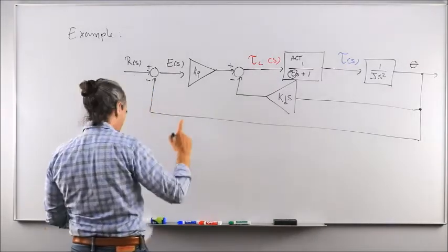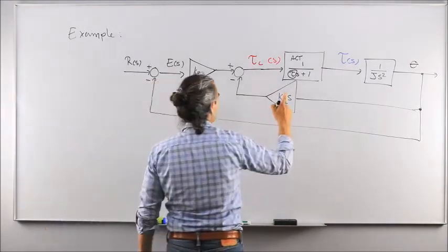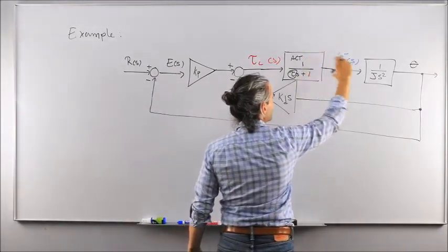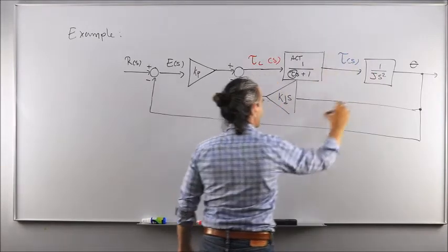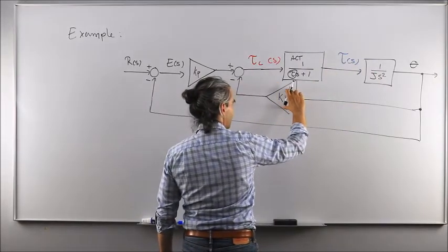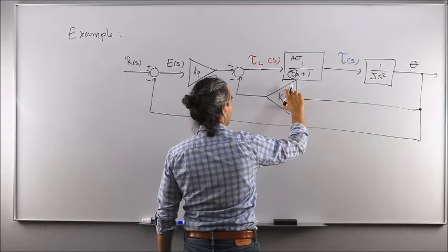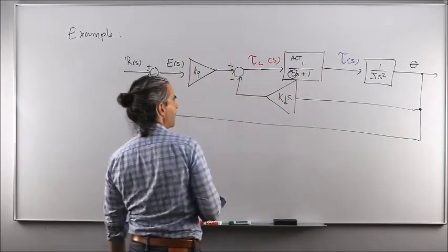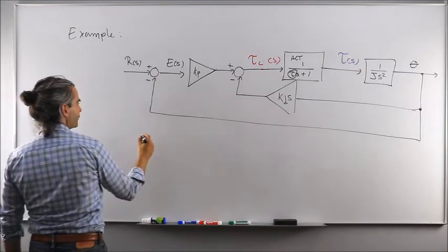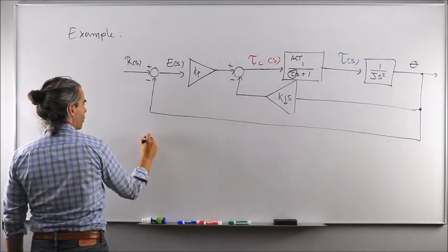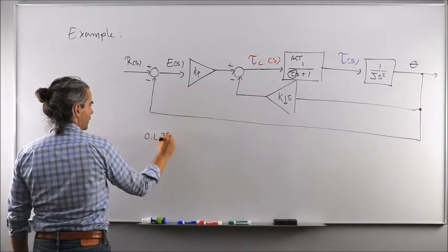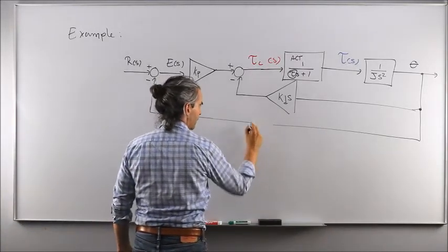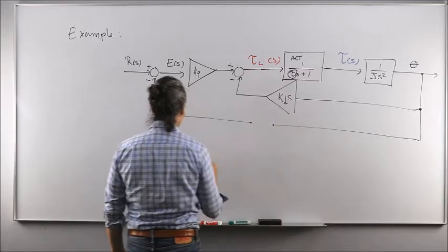Essentially, the closed loop transfer function can be done in 2 steps. First step is to do the series connection here, and with that in feedback configuration, and then as a second step another series with Kp, such that we end up with our open loop transfer function, obtained by simply disconnecting this branch.